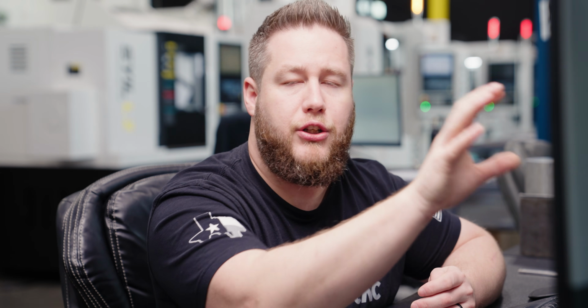Now what I can do is bring tools into my file, where before we really didn't need to do that, right? You just pick your tool library and it's going to use the tools in that library, or at least try to. Now I can actually bring tools into my session, into the CAM software, and then tell Cam Assist to specifically look at those tools as well. So I really am a fan of that.